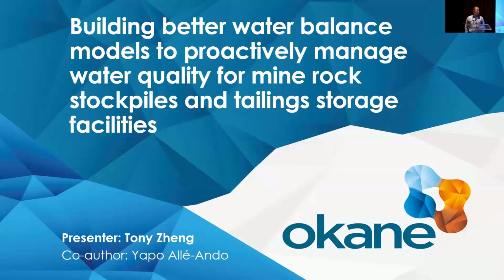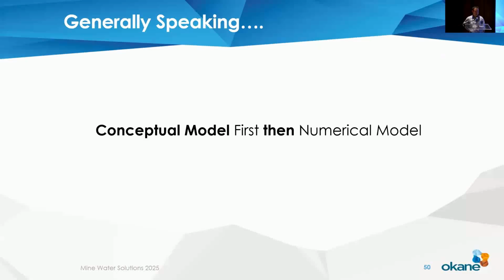Okay, let's get started. So the topic I'm talking about today is quite long-winded, so I'm not going to repeat that topic. But on the next slide, I'm going to show you what I really want to talk about today, which is the importance of building a better conceptual model. It is the first step, and it's the most critical step in building a better water balance, water quality model for waste rock dumps and for tailings storage facilities. Oftentimes we don't spend nearly as much time on the conceptual model phase compared to what we spend on the numerical model, and that's something we need to improve as an industry.